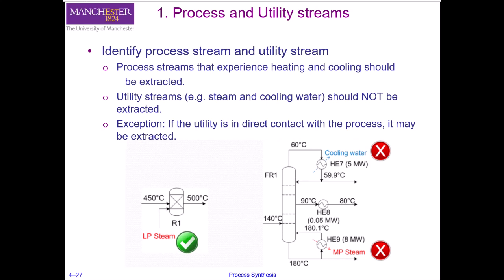We do not need to extract the data for utility streams unless that utility is directly involved in the process, and then we treat that utility as a process stream, and then we extract the data for it.